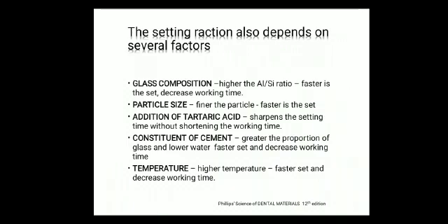The setting reaction also depends upon several factors. First is glass composition. If the aluminum or silica ratio is higher, faster is the setting reaction and it decreases the working time. If powder particles are smaller or finer, fast reaction will occur.